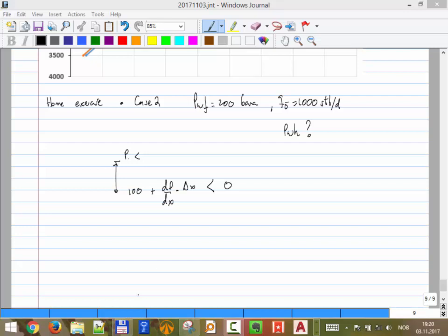Then we went to this very interesting concept of flow equilibrium. How do you find the operating point? Remember, you have two curves, one available and one required, going up. You can choose any point you want: the choke, the middle of the tubing, or 100 meters below the Christmas tree. It has to be consistent at any point that you choose. The equilibrium all the time has to look like that, one going like this and one going like that.